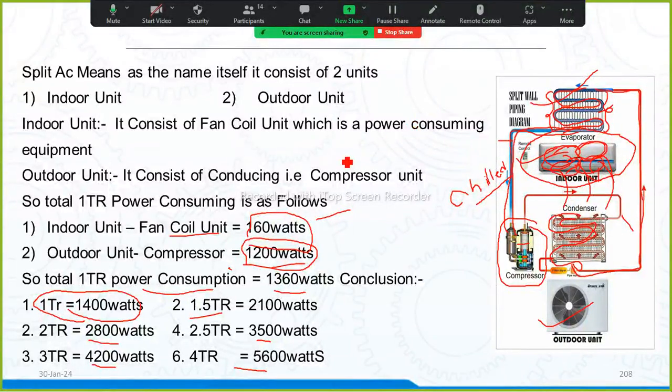Nowadays, when you are going with software companies or even small commercial buildings, if you have a slab where you have provision to place an outdoor unit, then we go with split AC only. But in some places we don't have any provision of placing an outdoor unit. At those places we need to go with the window AC.